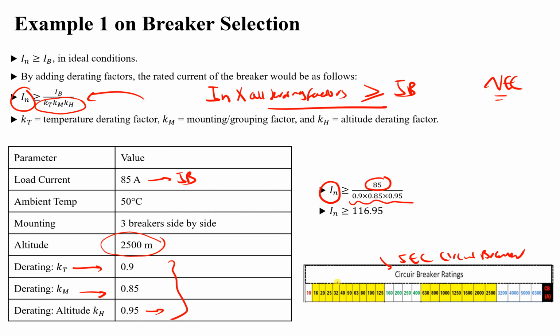For example, if you look at here, we have 1016 circuit breakers in IEC. If I remember NEC exactly, it was 15 amperes. So the derating, the circuit breaker values can be different in NEC from IEC. So you have to be careful what you are selecting or what type of installation or codes you are following.